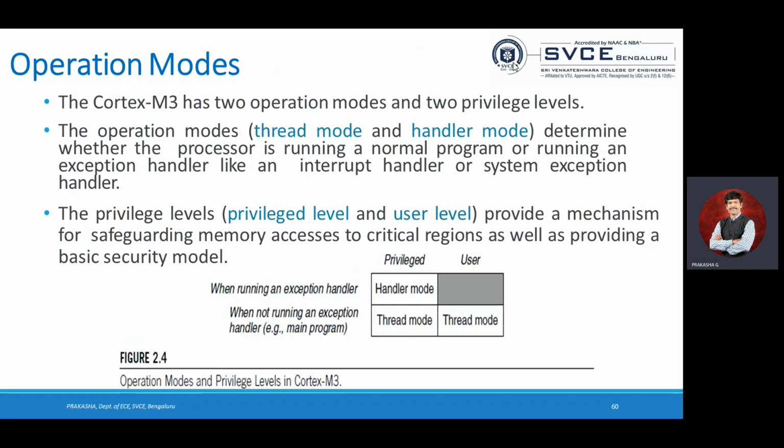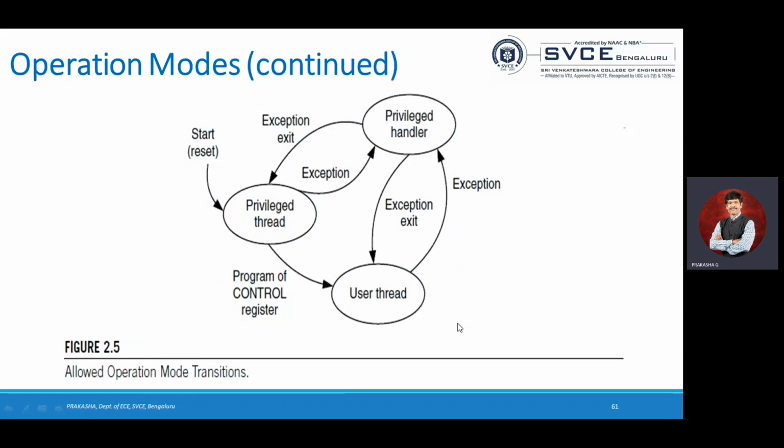If it is thread mode, it's going to be different. If it's handler mode, it's going to operate in a different mode itself. When running an exception handler, it will be in handler mode. When not running an exception handler, it will be in thread mode itself.